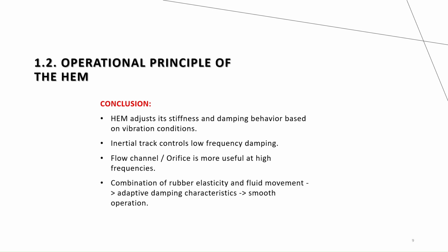In conclusion, we can say the hydraulic engine mount helps adjust stiffness and damping behavior based on vibration conditions. The inertia track plays an important role in controlling the low frequency damping, and the flow channel orifice is more useful at high frequency.